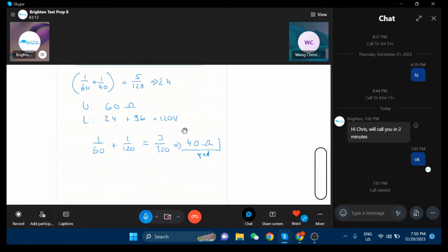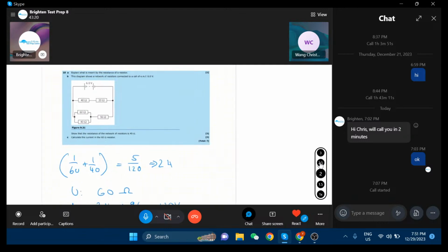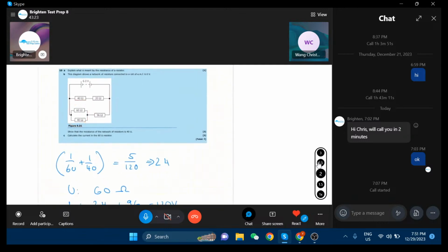Yeah. All clear. So you just play with it, in a positive sense. I mean, you just know what to do. That's good, yeah? You just say, okay, I see that one here. So I have the parallel and I have to deal with it. Afterwards, I get the total because it's in series. The series is straightforward, so I have these two. However, they are both parallels again, and so I have to do it. So you see exactly that bottom-up approach that you say first, I isolate that box, and just look at this one like you did, and I get the resistance of that stream as one box.